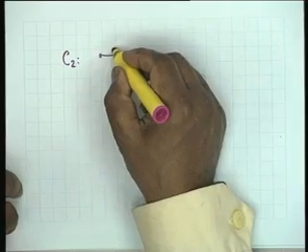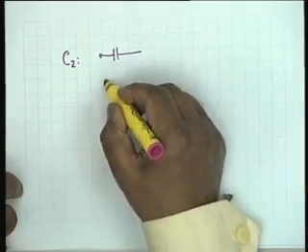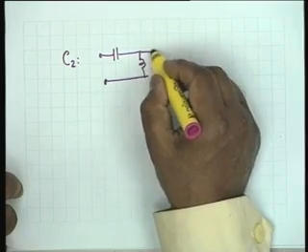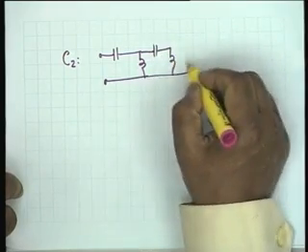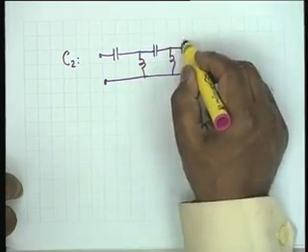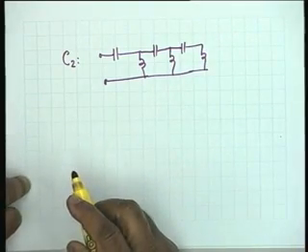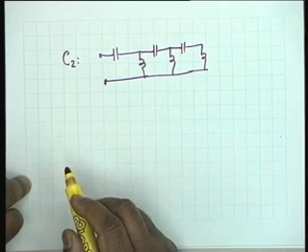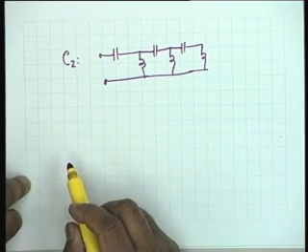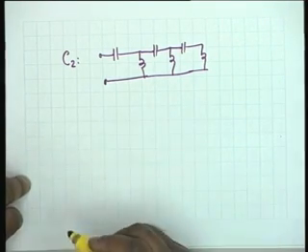As far as C2 is concerned, you have to start the continued fraction expansion with the lowest powers, starting from impedance. Therefore, you have a capacitor in series, and then you go on doing the ladder till you get 6 elements, and finally at infinity, does it have a pole? Yes, it does. Okay, so that is a check.